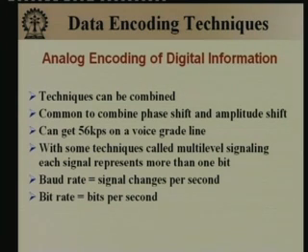With some techniques called multi-level signaling, each signal represents more than one bit. This is also possible. One is the signal which indicates the level of the voltage, phase or frequency, whatever it is, that is the level of the signal. The other is the bit or bits that it may represent.